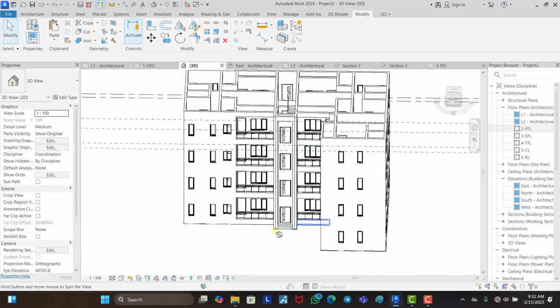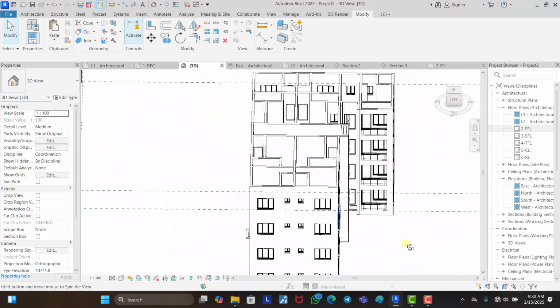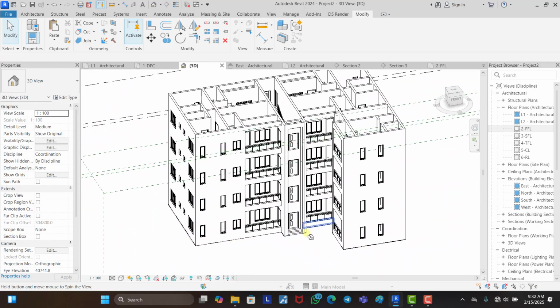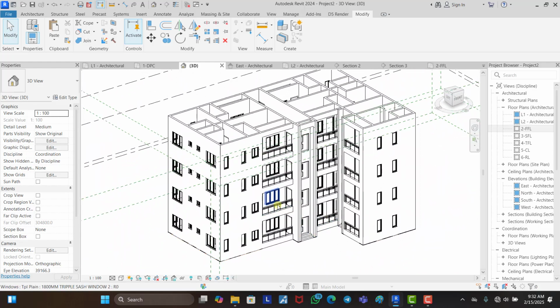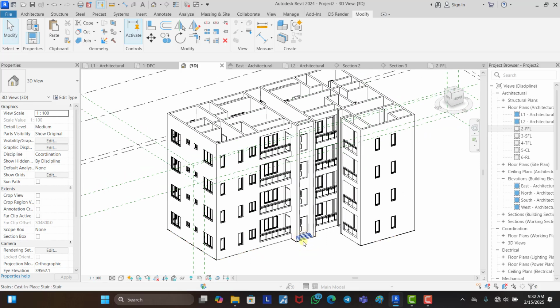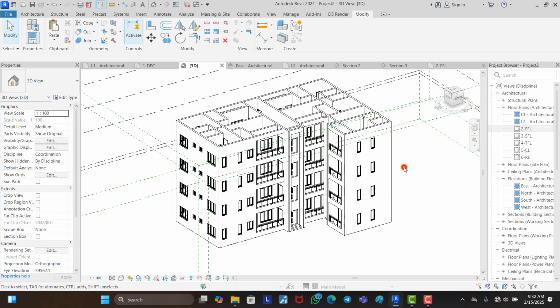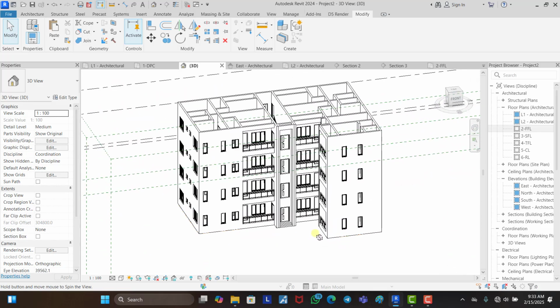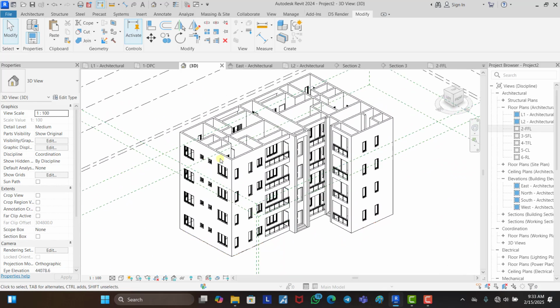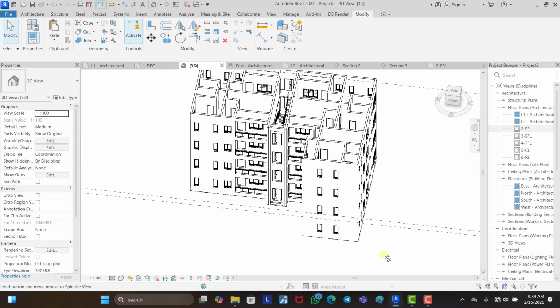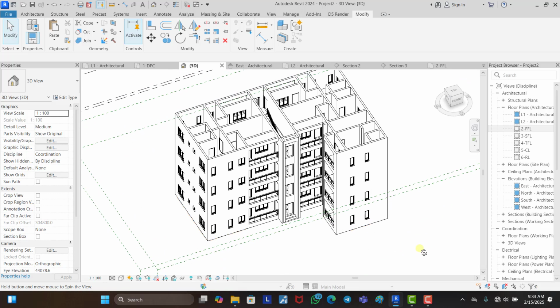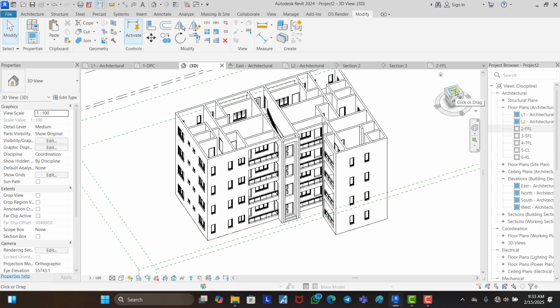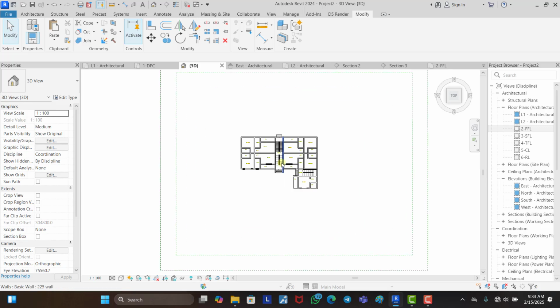Okay, there's nothing else to do other than to create our concrete fascia and our roof, then the facade materials and treatments that we need to do. Okay, so this is all for the wall, windows, doors, and all staircases. Then we need to create our concrete fascia. That's the next step. So for us to create that concrete fascia, all we need to do is to come to this top view like this.